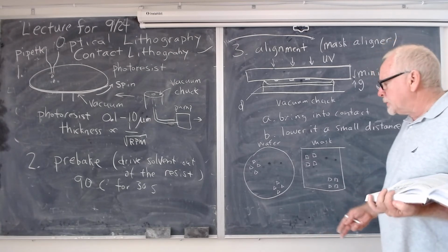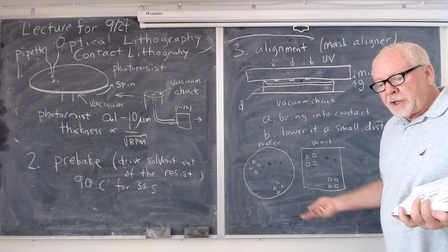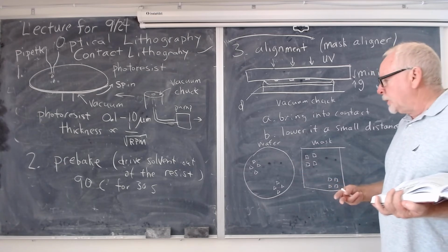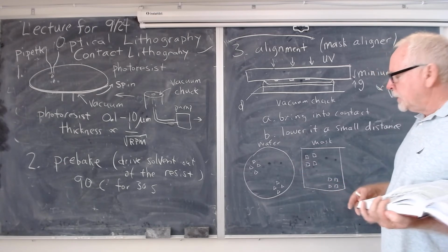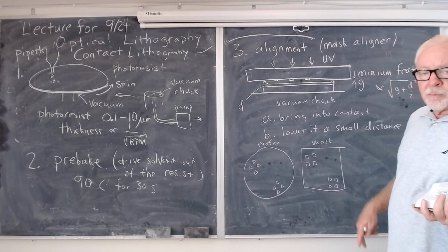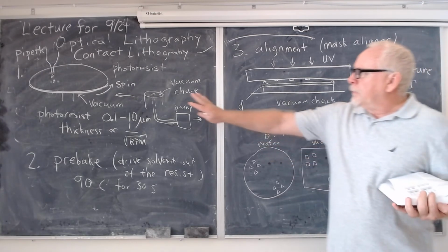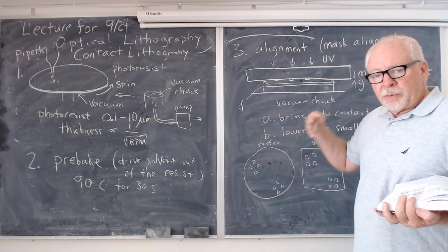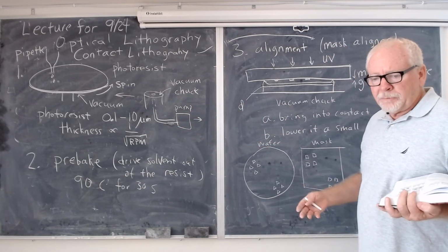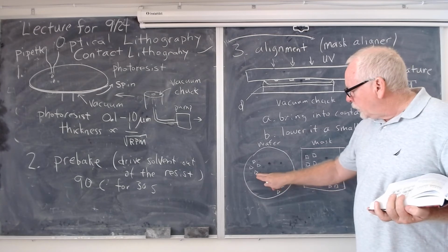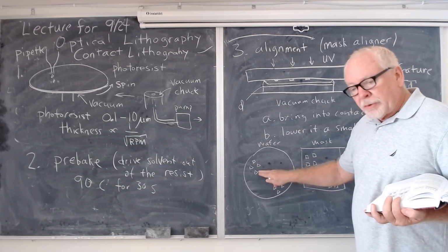And in fact, we're sort of jumping ahead, and we keep having to mix in recipes. Often your first step in any recipe fabricating a semiconductor device is to put down what's called alignment marks. So with a bare wafer, you might do an evaporation step, like liftoff, where you're putting down markers on the wafer.